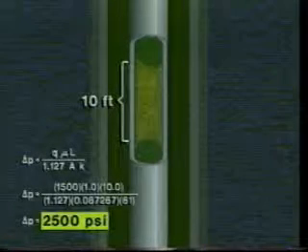This same approach can easily show that a 2,500 psi pressure loss would occur if a 4-inch diameter wellbore, producing 1,500 barrels of fluid per day with a viscosity of 1 centipoise, had a 10-foot sand bridge with a permeability of 61 darcies. This unit covered only the mechanical methods of sand control, those being the most common.